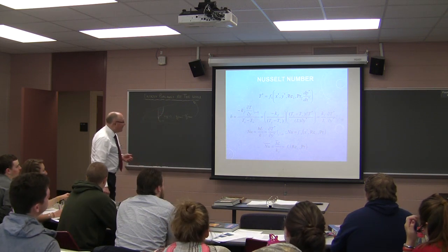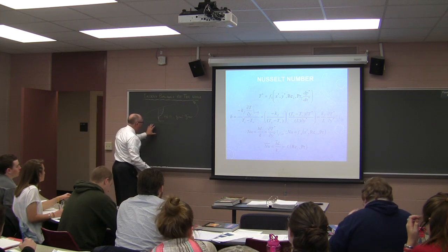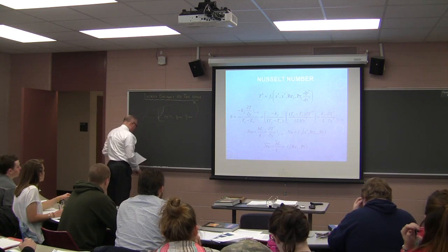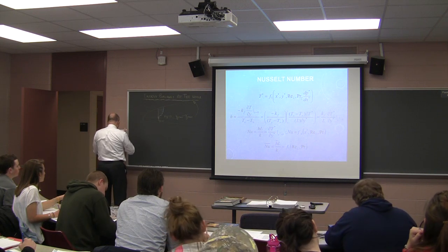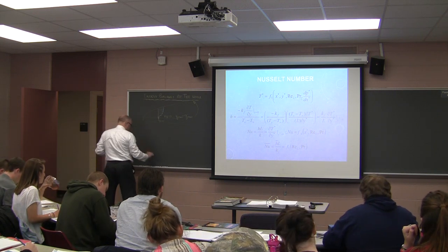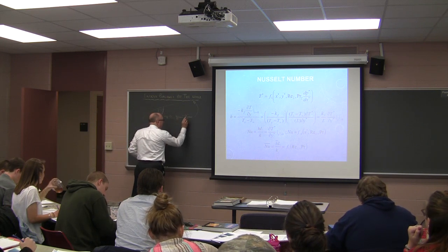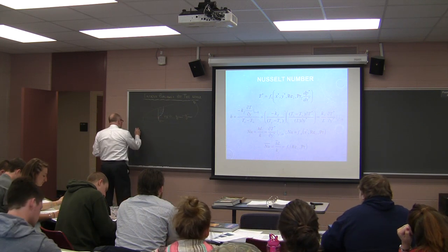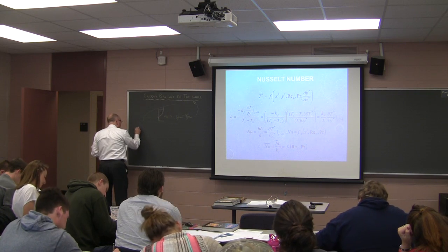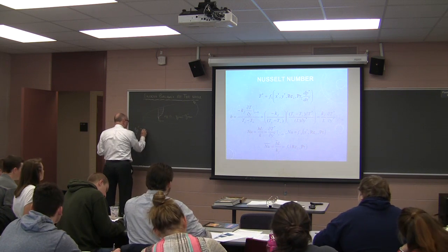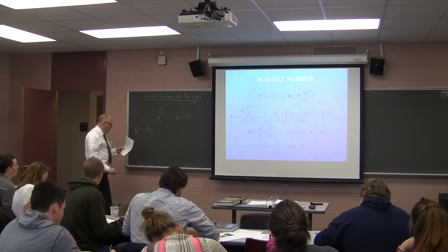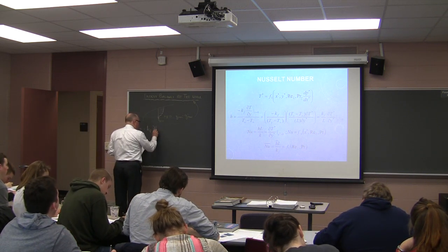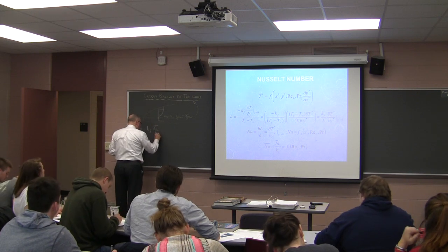So, this energy balance at the wall is a big deal. So, let's write the energy balance at the wall. We have conduction coming in, and I'm writing it in terms of the flux. So, Q at the surface, the flux, has got to be equal to minus Kf. Now we're doing the K of the fluid because we're talking about into the stagnation layer.